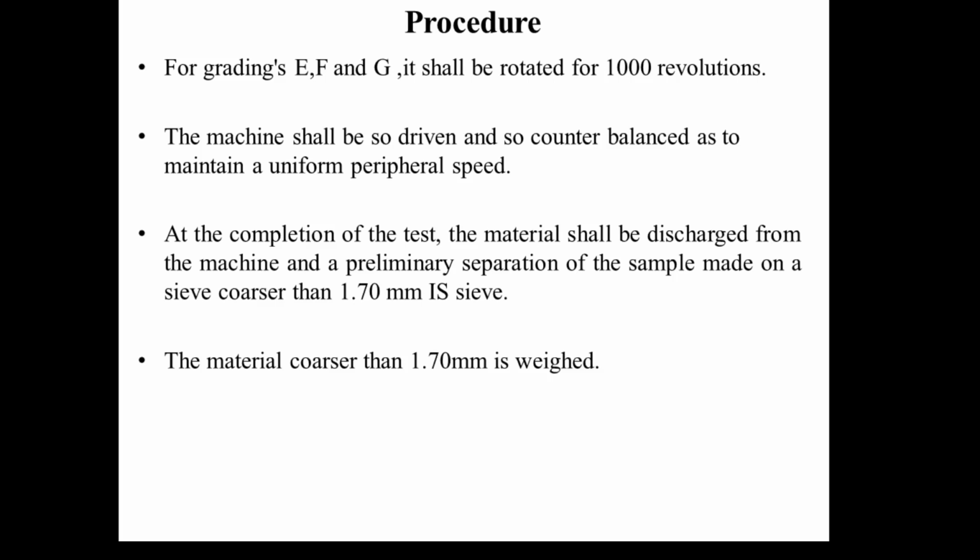At the completion of the test, the material shall be discharged from the machine and a preliminary separation of the sample made on the sieve which is coarser than 1.7 mm IS sieve. The material coarser than 1.7 mm is weighed.